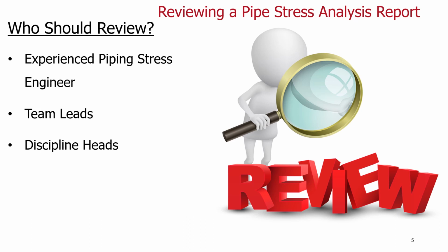During the review process, it's important to have individuals with expertise in pipe stress analysis, structural engineering, and relevant industry standards involved. The reviewer should carefully assess the methodology used in the analysis, the assumptions made, the input data used, and the conclusions drawn. Any discrepancies, concerns, or recommendations for improvements should be documented and addressed before the piping system is constructed or put into operation. So hope this point is also clear to you.